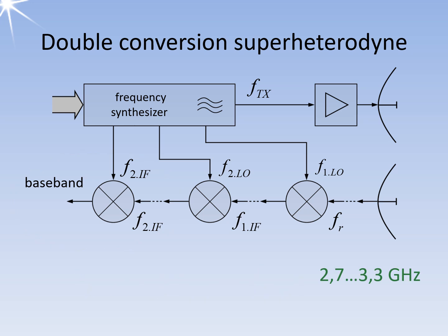To receive signals in radar frequencies within the S-band, the receiver needs to operate within a frequency range of 2.7 to 3.3 GHz while avoiding the risk of including an image frequency. Consequently, the first intermediate frequency must exceed 300 MHz. A value of 450 MHz, as referenced here, is sufficiently large for this application. Given these values, the first local oscillator frequency must be tunable between 3.15 and 3.75 GHz.